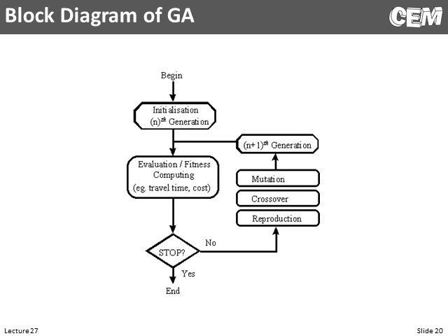So here's the basic algorithm. We initialize our nth generation. So this would be our first generation. Then, so that's our set of children. And maybe we have 20 children. We simulate each one of these and calculate our merit function or fitness function for each one of those. Well, if suddenly those fitness functions exceeded our threshold and we have a design now that's good enough, well, we can choose to stop.